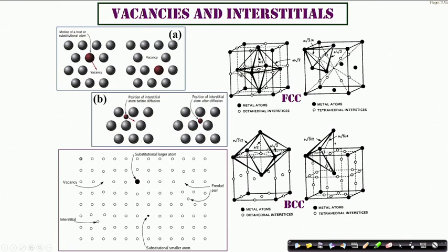But when you say that you expect atoms to occupy corners and face centering positions, then the centers of the edges and the center of the unit cell obviously are lying vacant. And the diameter of such a vacant hole is the largest. So this is how you can define a possible interstitial vacant site and its size in an FCC crystal.